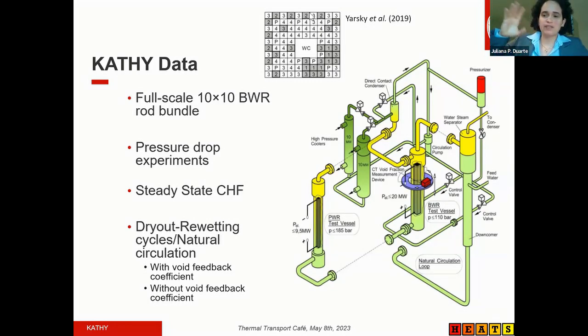We have 5, 6 thermocouples in each of these gray rods along the axial location where you'd expect to observe critical heat flux. Okay, so towards the top where you expect the critical heat flux to happen, is it averaged there? It is not averaged. We do not average them.